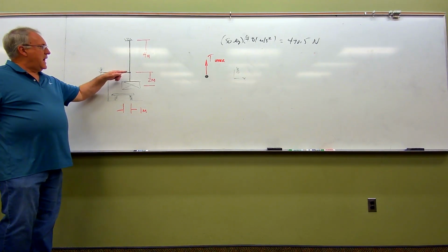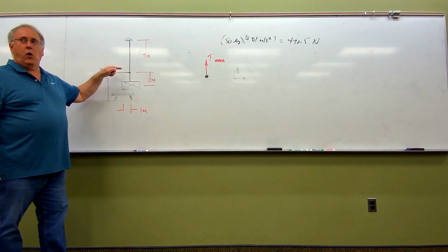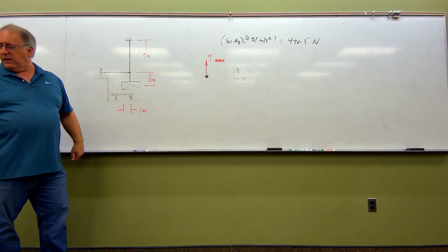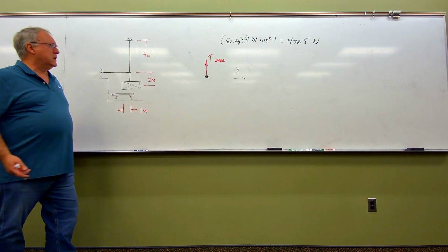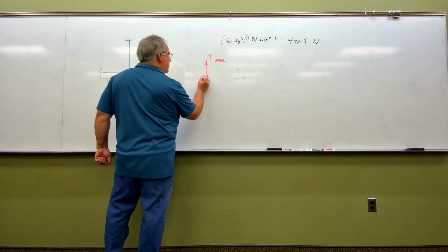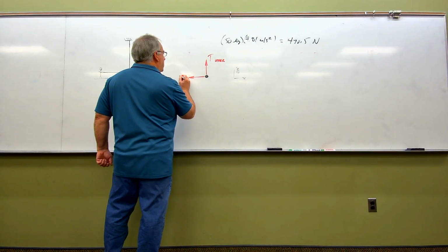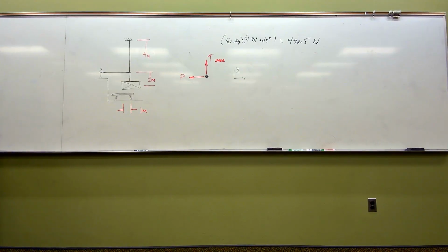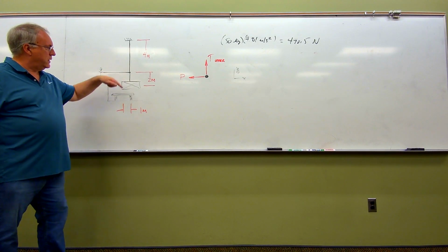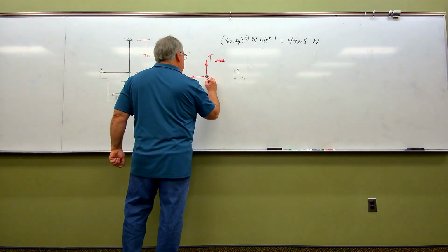And that knot used to be in contact with the rope that the worker's pulling on. Now the narrative referred to that pulling force as force P. So in that case, the tension in the rope must be the force P that we're looking for. And then lastly, folks, the knot used to be in contact with that cable right there, so we've got a force going down here.